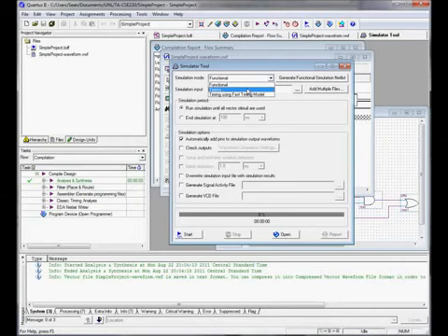Timing gate delays, and gate delay is when I turn the power onto something, it takes a little while to push through that device. Now I grant you we're talking electricity here, so this isn't very fast, or excuse me, very slow. This happens on the order of nanoseconds, but for our simulations, nanoseconds matter, and you'll see as you work on your project that certain things will start to delay how long it takes to get through your system. So the more components you have in your path, the longer it's going to take. That's what the timing analysis will tell you, and it'll be really instrumental in helping you to discover timing issues that are going on in your circuit. For instance, something's happening on this part of the circuit, but it needs to be to a different part faster, so you can kind of fine-tune that.